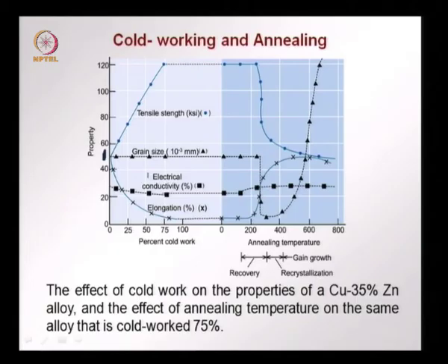In this plot we also have electrical conductivity, which decreases slightly due to cold working, and we recover that as well during annealing. So these are the different processes that occur during cold working and annealing.